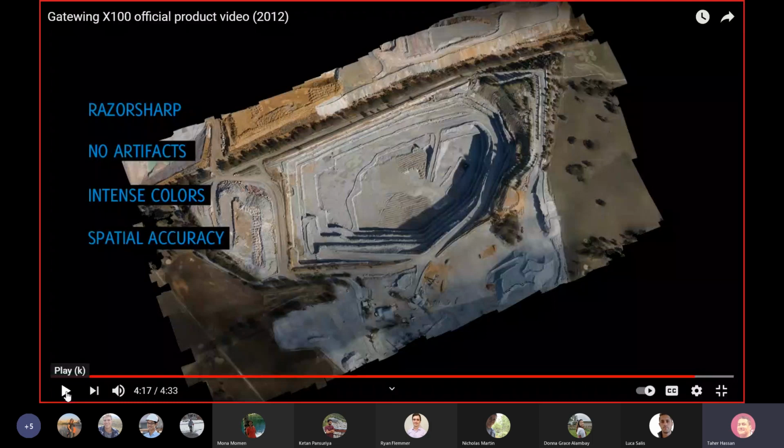So they have their own different app, in which they have to pick the area and set where the drone will fly from, and then the app will take over and control the drone until it covers the entire area. When it comes back, you just do the processing after you download all the photos. So this is one discussion I wanted to make sure you understand: although we have different kinds of drone designs, the process is still the same.